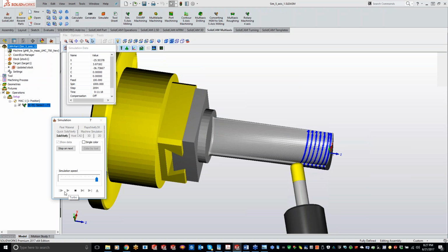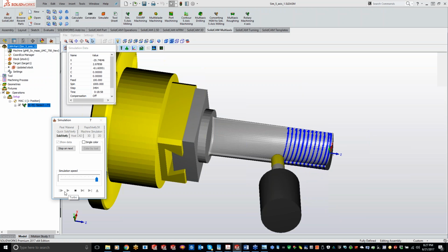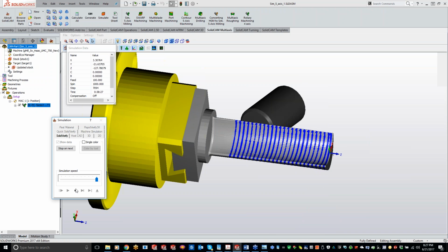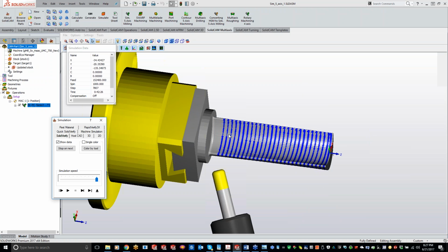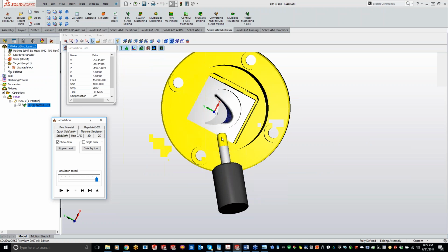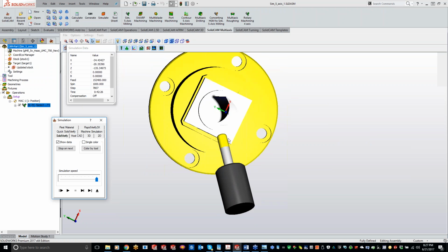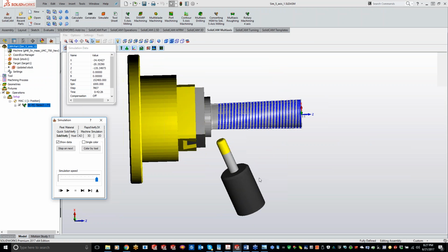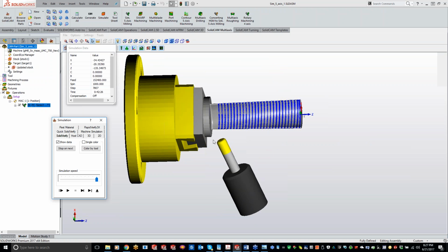Kevin, this is where a 5-axis simultaneous machine can really save you a little time, right? Oh, absolutely. Because you have so much more flexibility. Yep. So now you can see we were able to get that tool even farther in there. I'm kicked over at the 20 degrees to the tilt, but also we're tilted 20 degrees this way, so kind of coming down. I can kick that over just a little bit farther, but I'm really not going to get too much closer in there, because I'm going to start running into my holder here. So I would say right there is good.